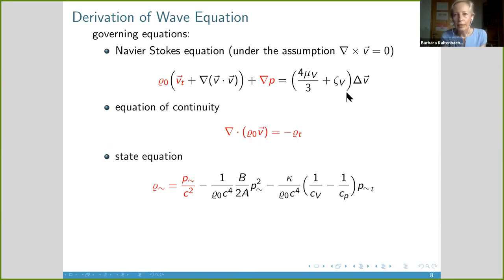You would maybe say that also this part is linear, but it's related to some dissipative or viscous effect. And so therefore, at first order, it is supposed to be skipped in the derivation of acoustic equations. So it's the linearized balance of momentum, the linearized balance of mass, and this linearized relation between mass density and pressure via the speed of sound.